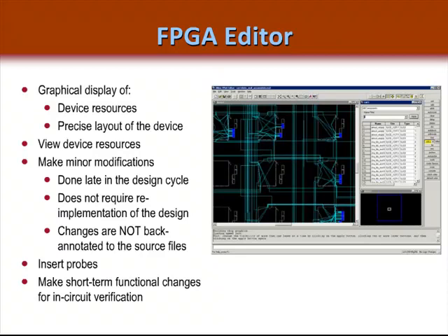But be careful, you're actually placing and routing the design manually, which means if you make a mistake, it's your mistake. So be sure to keep a copy of your last implementation result and then create a new place and routed design file after you're sure you didn't make any mistakes. After your changes have been made, you can create a new bit stream from the final NCD. The NCD, that is a native circuit design, which is the primary output of the place and route tools.